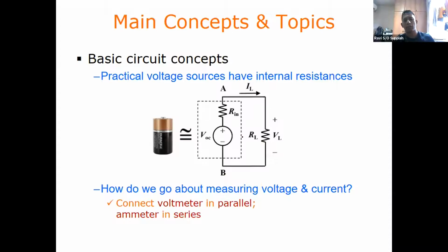Of course, when we draw circuits, sometimes we will draw it in this aspect. Sometimes we may just draw it just like that, and then we say this is the load, and this is 5 volts, for example. So you must see the question and the context. In some cases, if we say this is 5 volts and this is the load, calculate the current, and there's no other information given, then we can say that this is treated as an ideal source.